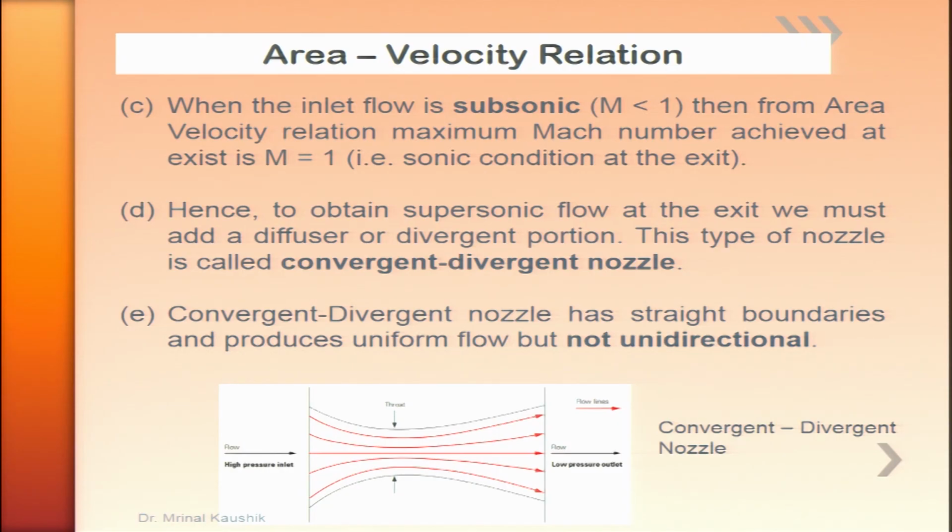For that you contour the nozzle, that is, the boundary itself is properly contoured, using a concept which we will discuss in a later talk, termed the method of characteristics, for two-dimensional flows, where computationally we contour the nozzle, and based on this design we form the nozzle for practical application. The idea is to obtain a unidirectional and uniform flow, so that thrust vectoring can be avoided in jet applications.